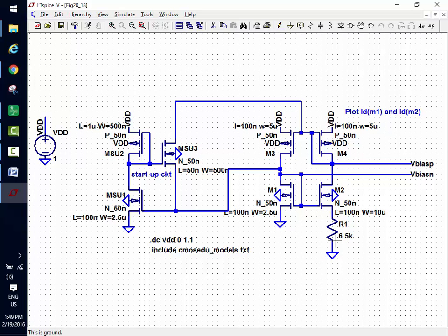So this part, really important, but once it starts up, we don't even pay attention to it. Okay? So this is the beta multiplier, and you understand, there's your PMOS current mirror, forces the same current through each side. There's your device. Notice how its W is 10, and here W is 2.5, so the K is 4. And then we again have a 150 microamp GM, etc.